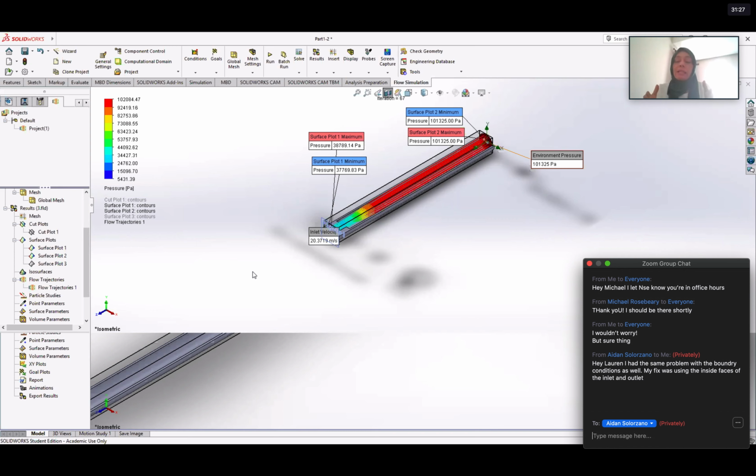Because we chose the area to be so long, we want to ensure that the flow returns to fully developed laminar flow. It will have time until all the turbulence from the vortices goes away and the flow returns to laminar at the exit.